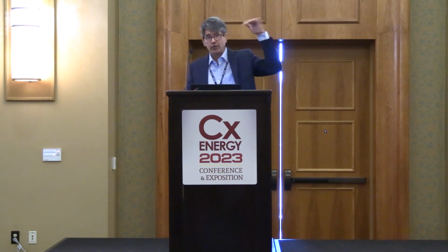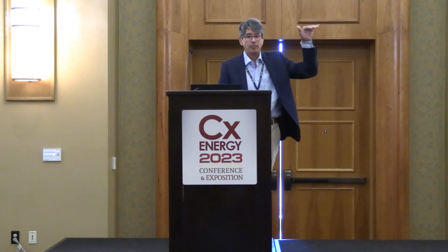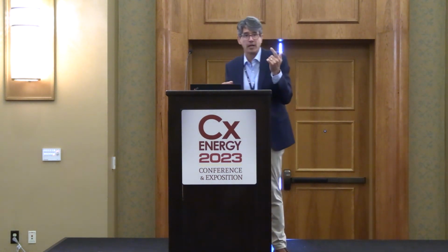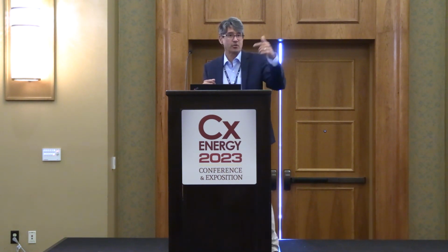Theater seating, always a big one. Auditoriums, that type of thing. You've got your ductwork, grills up high, possibly architectural features covering it. Seats are not in when all this is getting installed, right? Scaffolding's built, lifts are there, everything's going great. Okay, we're starting to put all the seating in, and equipment's still not running. So we can't even get in there to look at the ductwork, get to the grills, do a duct traverse, get to the balancing damper. What kind of access is there going to be for that?